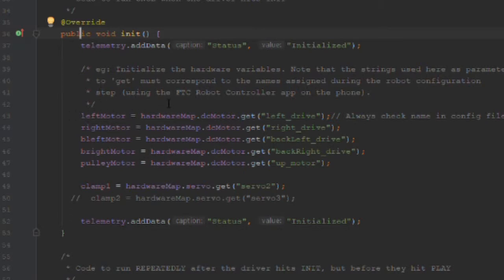Now, what's important to understand about this hardware map is that, at least with the modern robotics wiring system, and I'm not sure if this applies to the Rev system, it specifically assigns motors to random locations. So whatever you wire up your robot to, you have to go into your phones and hit configure motors to make sure that each motor is in the right spot. So whatever you name it, that's not automatically where it's going to go, because the phone doesn't know that.